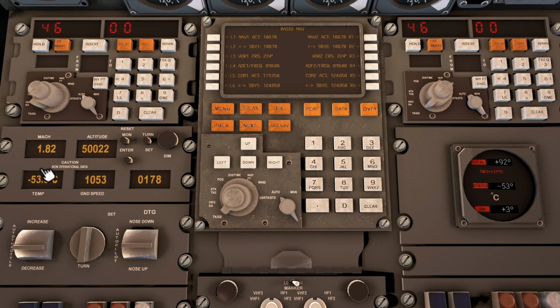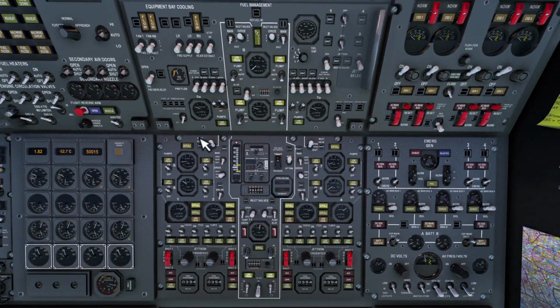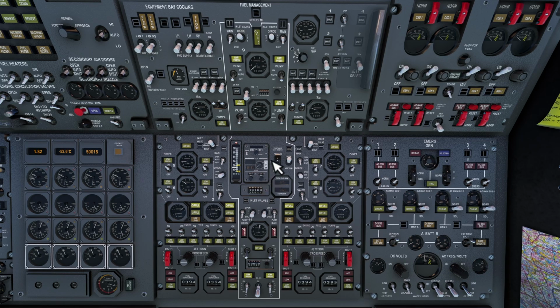Bit too slow. That means we're going to accelerate first before we are going to climb again. Trimming situation. Tanks are emptying. Even a bit under 59, so I actually pump the last fuel that we have in our front tanks, and this time also back to tank 11. Turning on pumps, opening valves, closing them. That's the part of the trimming of the Concorde. Very, very unique.